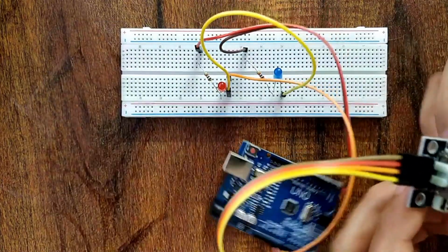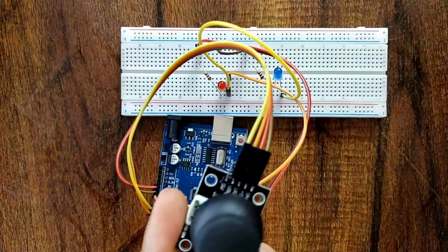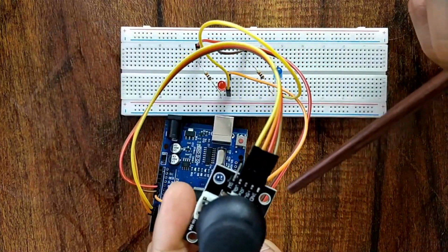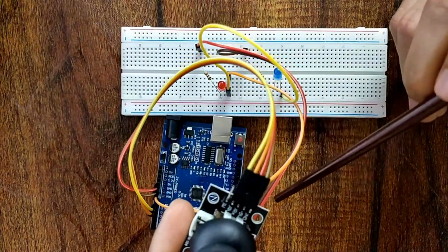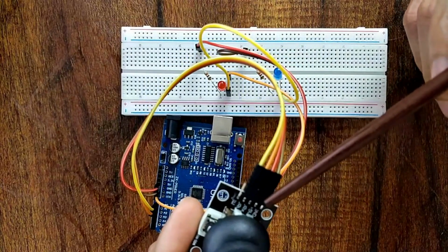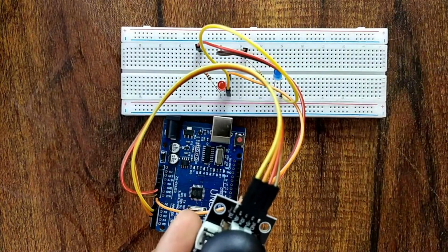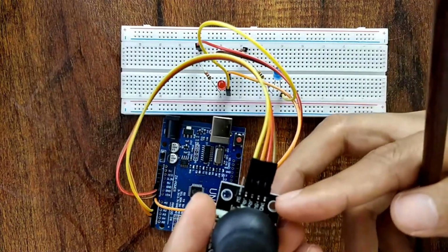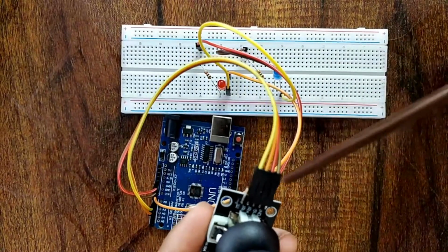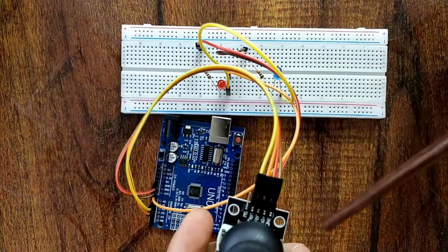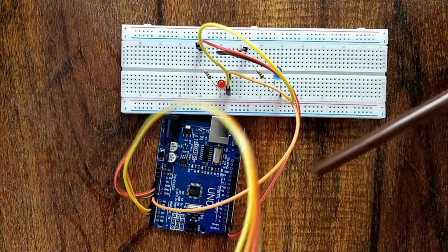As we can see, here are 5 out pins. The first one is ground and the second is the power supply plus 5 volt. Both of these are taken from our Arduino board itself. VRX and VRY are the analog out signals, which are given corresponding to movement of this joystick button in either plus X, minus X or plus Y and minus Y direction. The last one is the switch. If we press this joystick button, this switch output goes high, otherwise it's low.